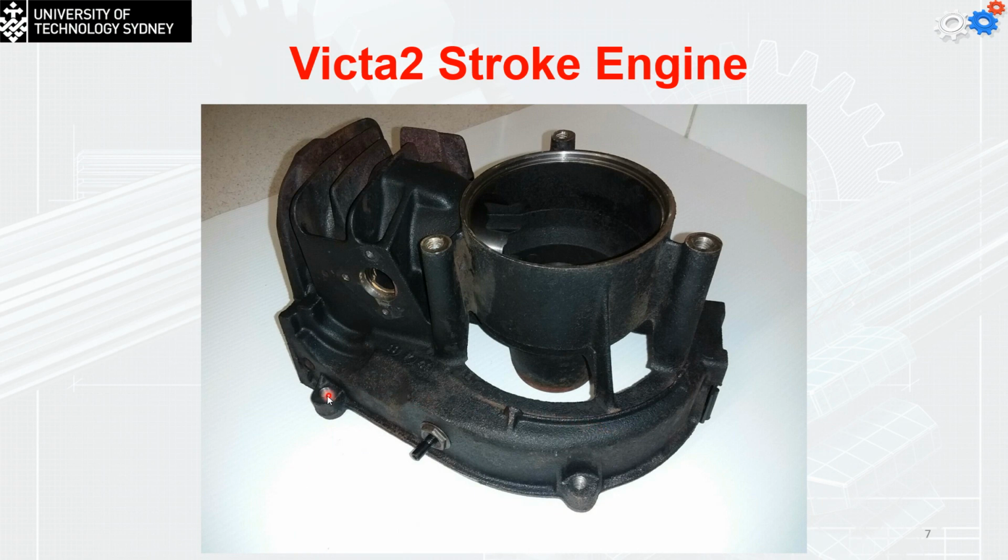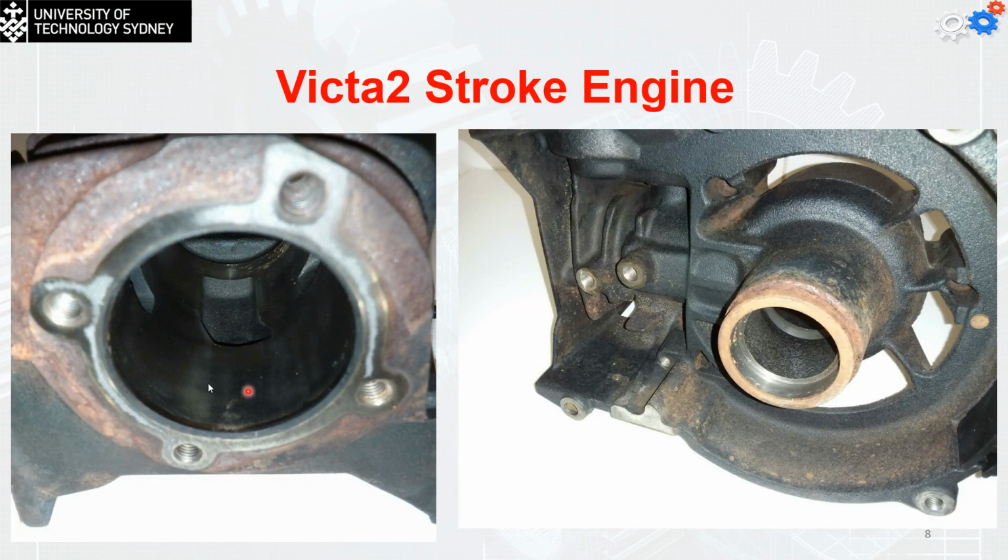For example, the location of these holes, which is going to be used to connect the engine block to the other parts of the engine, and also the quality of the seal location, the quality of the cylinder bore. It should have quite a good surface finish, and we do it by an operation called honing.